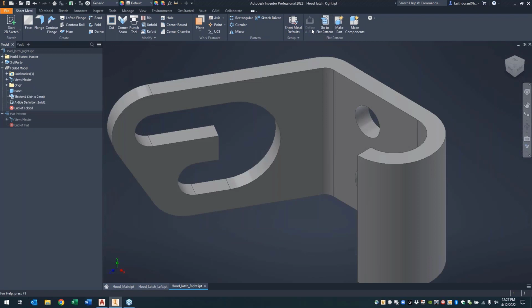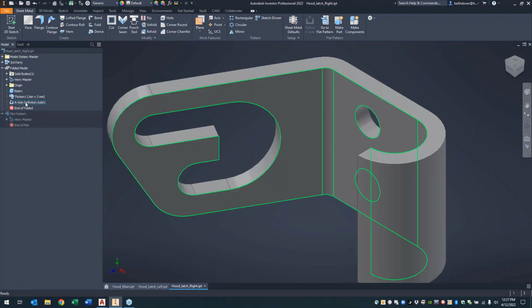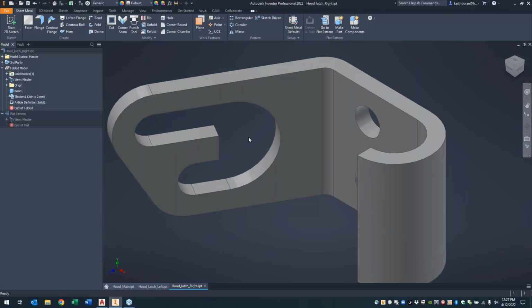And that step of defining the A side is not absolutely critical. You don't have to do this step, but for generating bend notations and defining, especially for neutral components, it's really helpful to define this to make sure it's understood what face is the inner or outer face set. Inventor doesn't have a here nor there to work off of on a neutral solid, so it can really help.